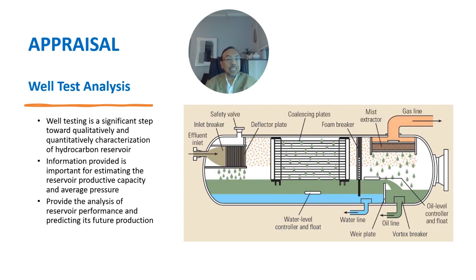Well test analysis. Well testing is a significant step toward qualitative and quantitative characterization of a hydrocarbon reservoir. Information provided is important for estimating the reservoir productive capacity and average pressure. Well test analysis also provides the analysis of reservoir performance and predicts its future production.